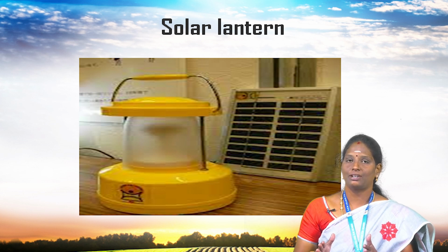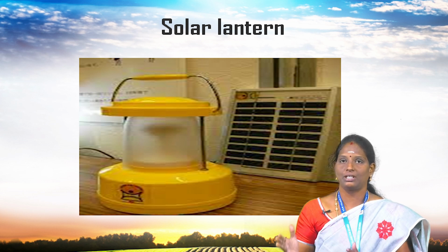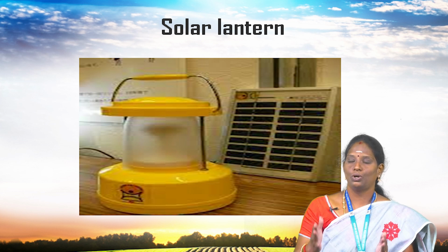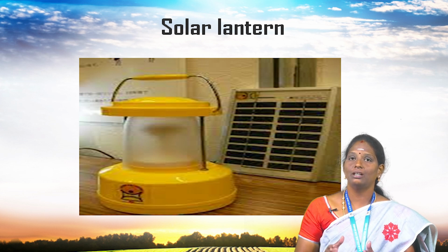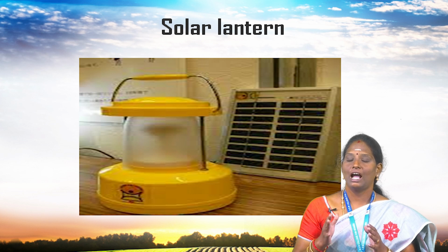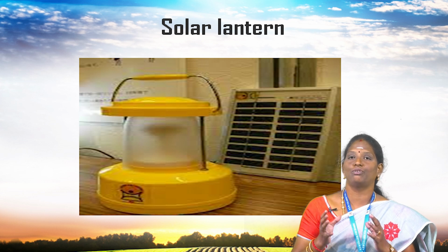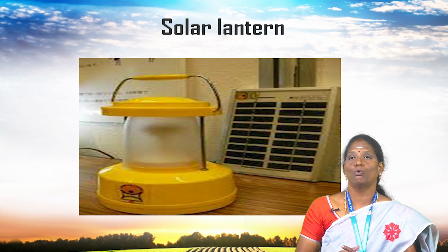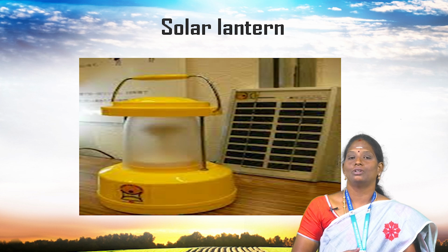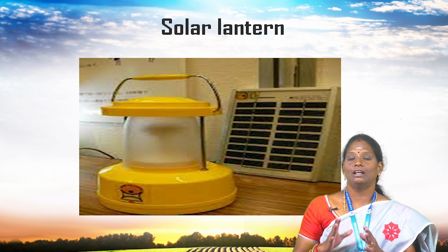Sealed nickel cadmium battery is a good option considering the deep discharge characteristics. It is important to have reliable electronics to operate the lamp and provide suitable protection. A high frequency inverter is being used to excite the compact fluorescent lamp and a charge controller which protects the battery from overcharging. So today we discussed what is meant by solar energy, how the solar radiation takes place, and the uses and applications of solar energy.